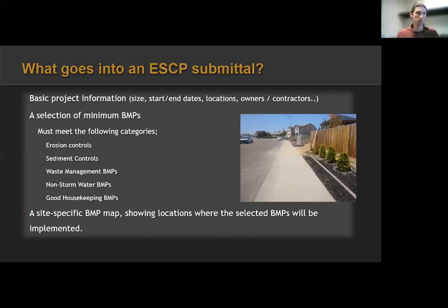So things like that, it's important to look and make sure all of those details are actually described in the erosion sediment control plan, because trust me, while it might not be disturbing soil, you're still going to be driving through unstabilized soil in a bare field, and that has potential for needing erosion sediment control plans. So having a site-specific map that has detailed locations of BMP implementations is imperative. Otherwise, you won't know what is actually going on in the project.